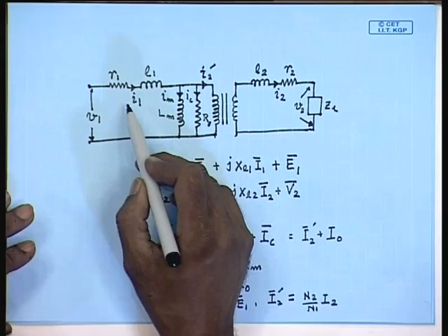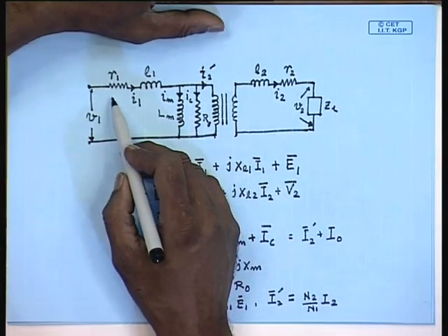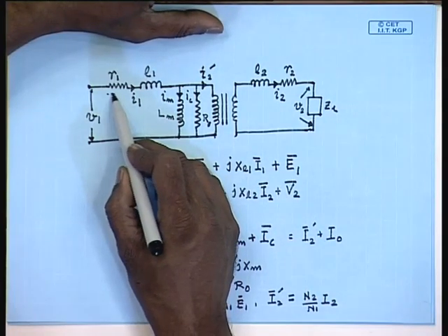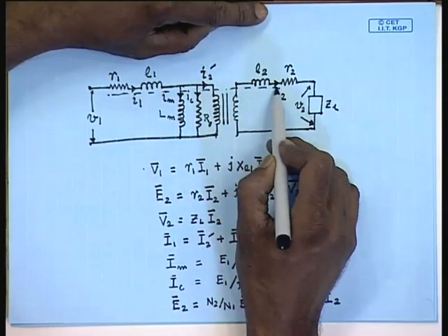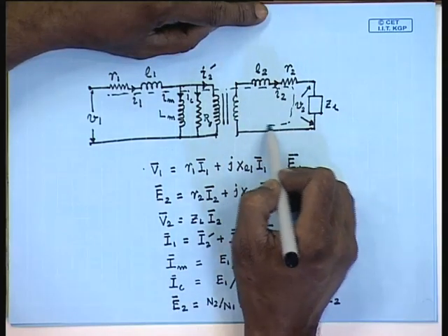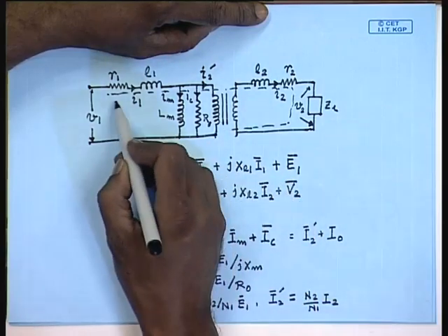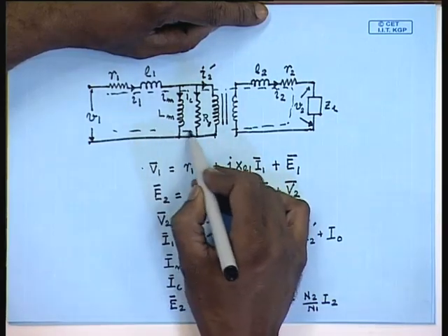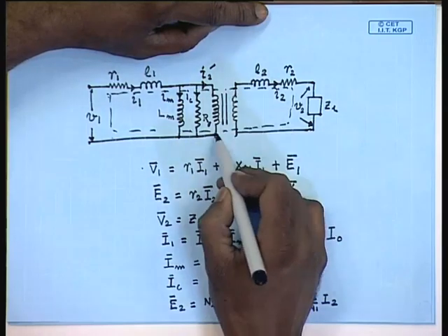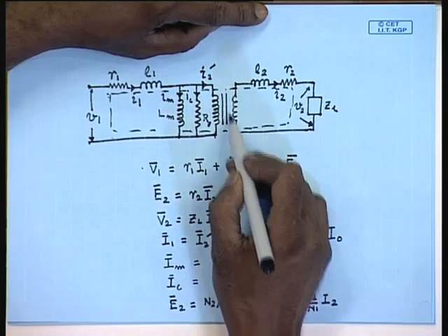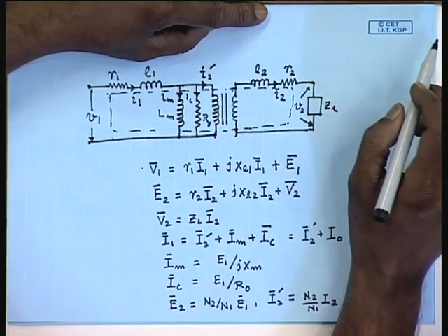Hence, we cannot apply, for example, a KCL or KVL where the loop current is expected to flow across the ideal transformer. We cannot write a loop equation involving such a path, since we do not know the voltage drop across the ideal transformer.